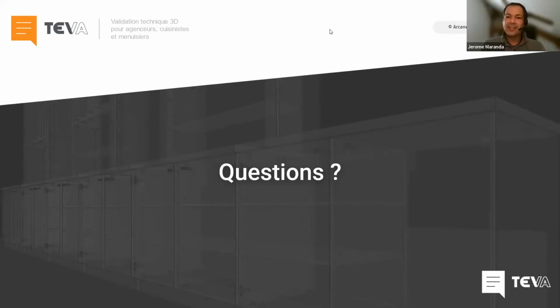Wait, Jonathan, there's one question, so I will just answer it. The question from Alexander Brown: will it also take the 3D DXF from CV? Yes, it is the same loader as Vortex Space, so we are able to do DXF with Vortex. The only thing is that because it's the DXF, we are not going to have the object tree, because the annotations are not included in the 3D DXF.